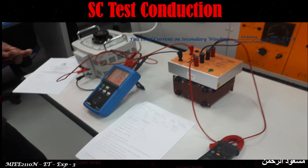In the theory we have discussed, there are two losses in the transformer: core loss and copper loss. Once you find these two losses, from the VA you can calculate the secondary output power of the transformer. From the output, we can calculate the input, and then the efficiency.